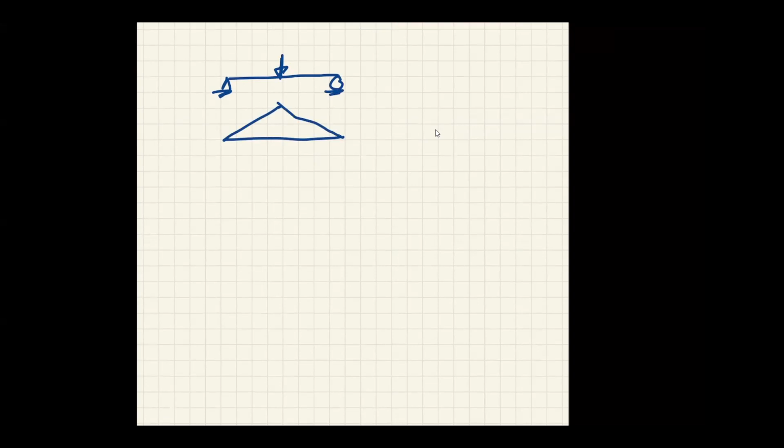So if I put the bending moment diagram on the beam, let the bending moment diagram be the load on the beam. If I solve this beam, the shear at any location of this beam that has the bending moment diagram as a load. In fact, we call this a conjugate beam.